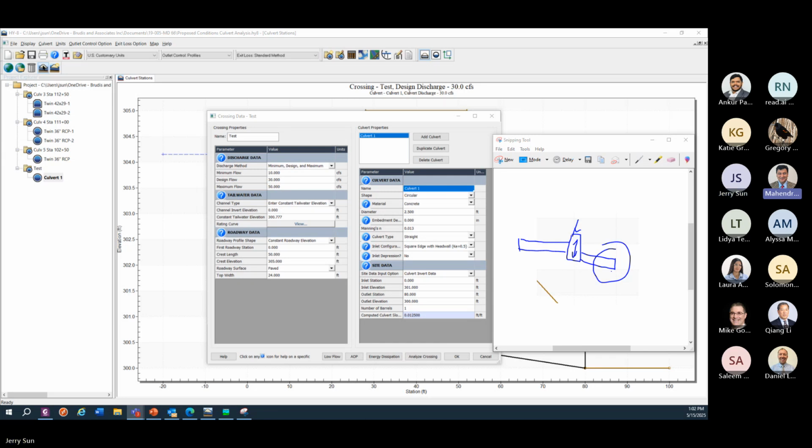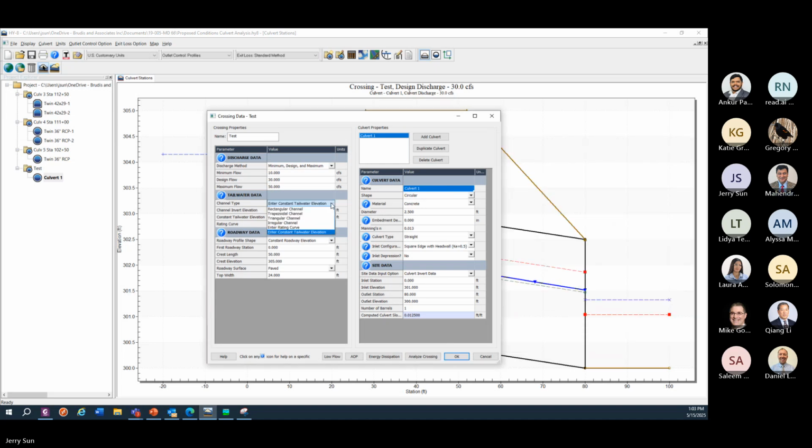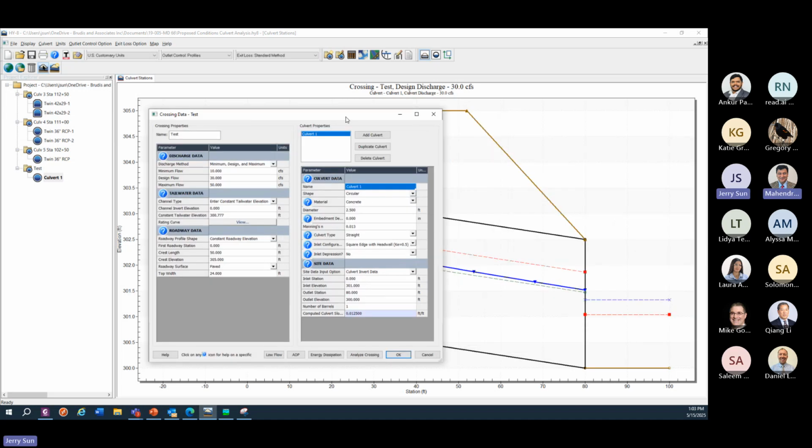I'd like to show something very quickly. Can you draw a trapezoidal channel? Station 0, this elevation, and station 10, 20. We just go from left to right for the stations and give the elevation of the irregular channel as the natural condition. If we plug that in, it gave the best result in my analysis when I did it. So Jerry, can you show that little sketch? You mean the downstream cross section?